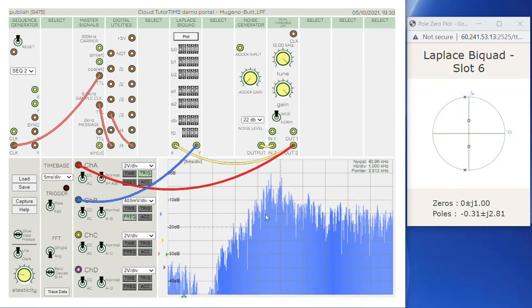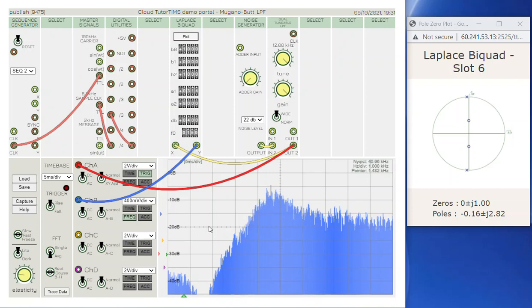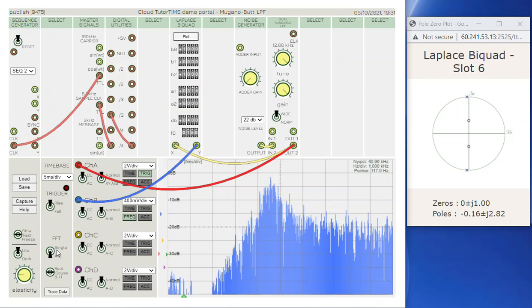By careful placement of poles and zeros, we can design or optimize a filter. And the purpose of this demonstration is to show you there is a relationship between the mathematics of the transfer function, the numerator and the denominator, as expressed in a pole zero diagram, and as it implements in the real world as an actual filter response. So there's a complete relationship between these three, shall we say, entities, these three properties, these three concepts.